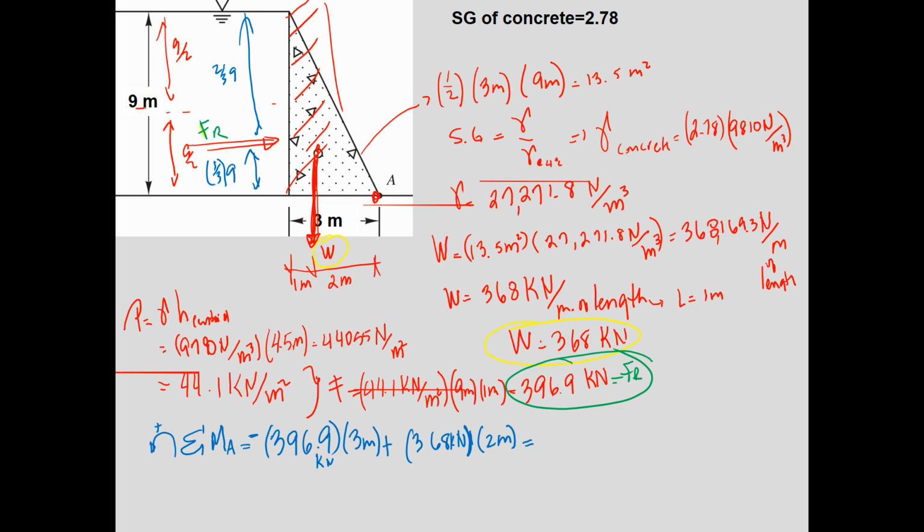So here, the resultant moment is negative 454.78 kilonewton meters, and it's in this direction. So the moment from the water induced by the hydrostatic force is larger than the moment that counteracts it by the concrete dam. So the answer is no, it's not safe. Thank you.